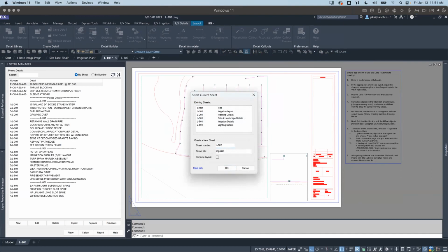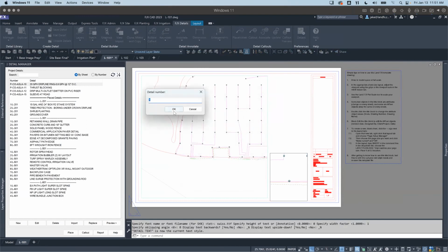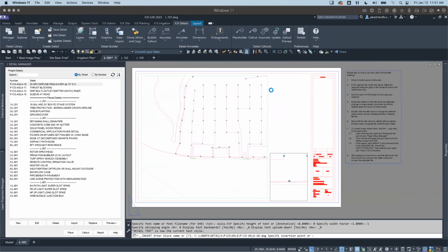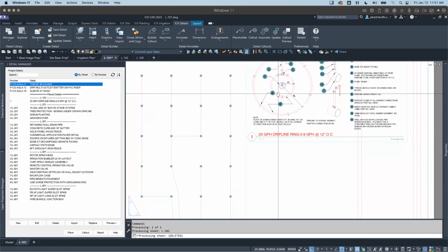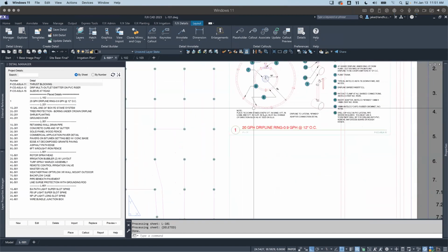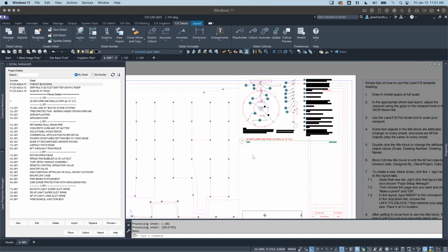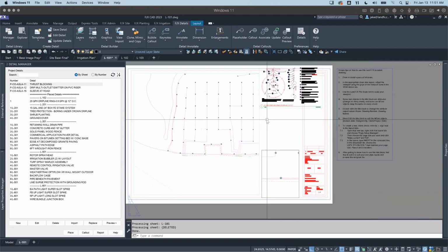102. I forgot that I was already setting things up. And we place this detail into this drawing. He's a little overlappy, so ignore him. But you can see that his line types are also all consistently showing up. So we can have all of these different scales set up if we are XREFing that final working drawing into an actual sheet and setting it up that way, okay?